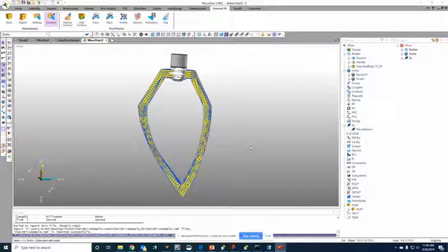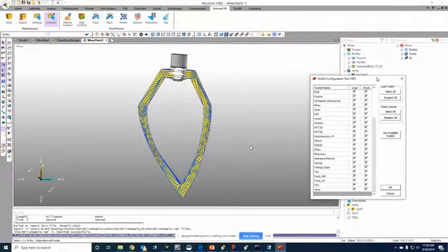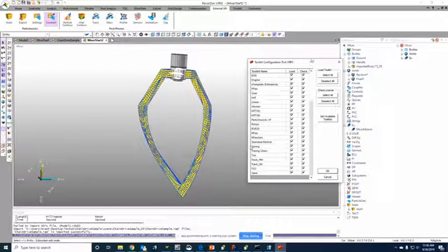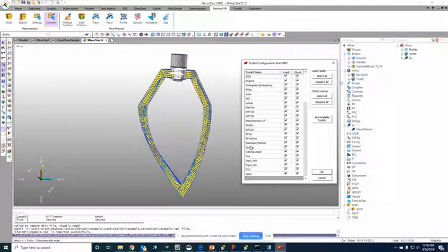So Mark, did you make sure that that XML file was inside the standard particle interface folder? I'm going to bin, solver, co-simulation. So yes, it is right there. COSIM, and then the standard particle interface XML.